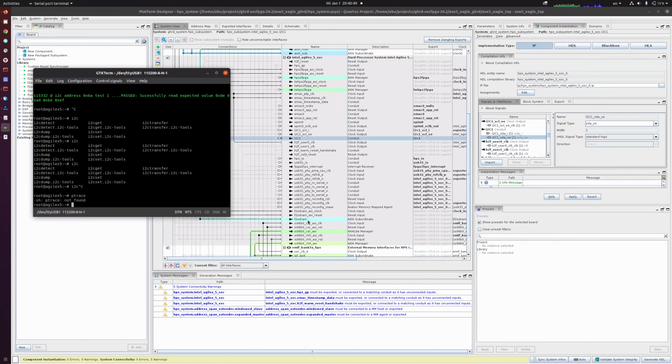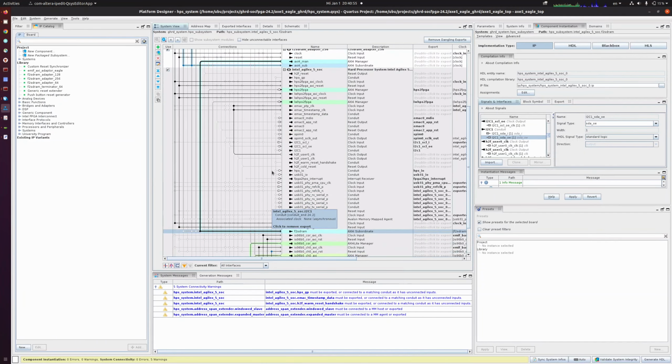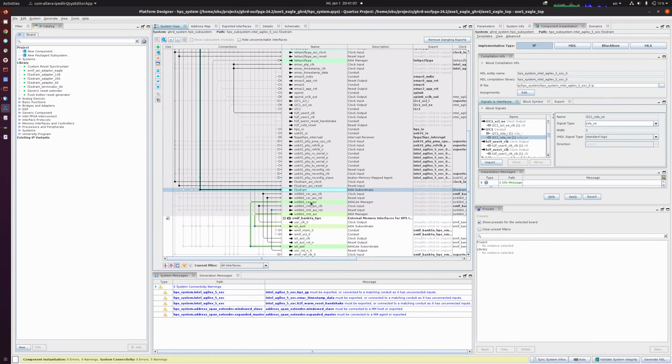Especially these RAMs, I would like to understand how. I guess I need to compile a C code to mmap and then address this stuff. The idea is I want to use these bridges and so on, and for this I need to somehow address the hardware addresses, the physical addresses, and I can use mmap for this. So I could write a C code with mmap and then access the stuff.